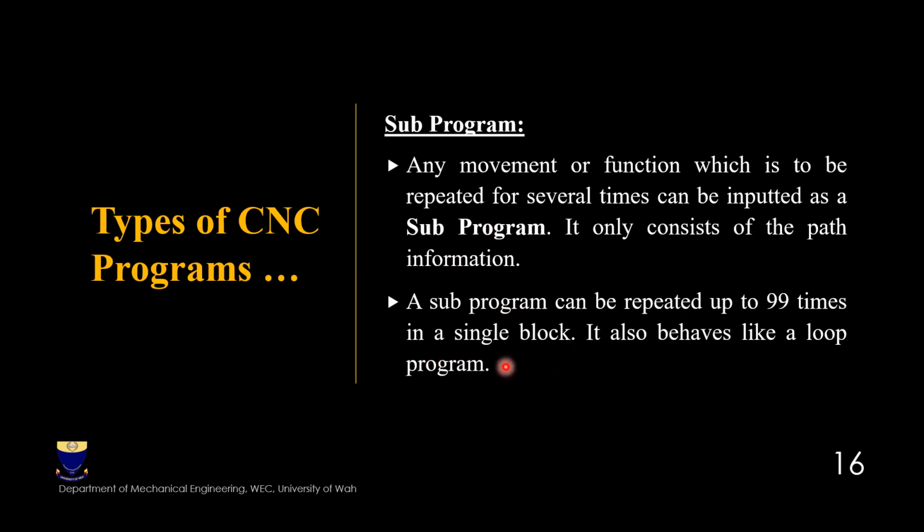A subprogram is used where you have to give the depth of cut. You give the depth of cut in a periodic way, like 0.5, then 0.5, then 0.5, then 0.5. In all given depths of cut, the profile or the contour is the same, just the depth keeps changing.